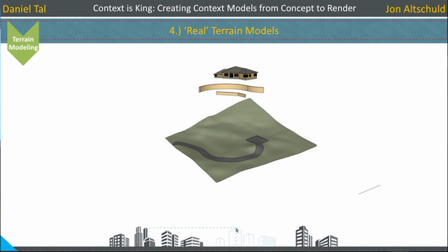Then I model the walls and the buildings, and I drop them down on the terrain. Then we're using another tool, Tools on Surface. Basically, we're cutting out this terrain piece, and that's our extent, our grading extent. Cut the hole out, and then using a very simple process, we start going in there and regrading the site based off our desired look and feel. You can start measuring out some of the grades in there, make it seamless.